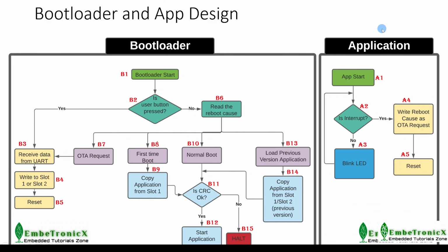Now we will move to the application. Once the bootloader starts, it will check the GPIO, and if that is high, then it reads the reboot cause and assumes that this is a normal boot. It will verify the CRC, and if the CRC check passes, then it runs the application. So it will come here.